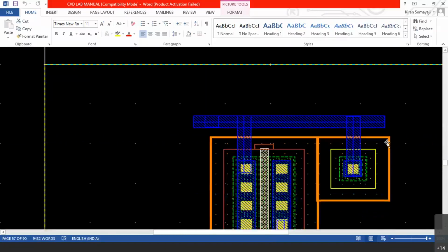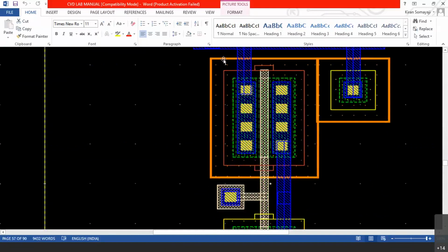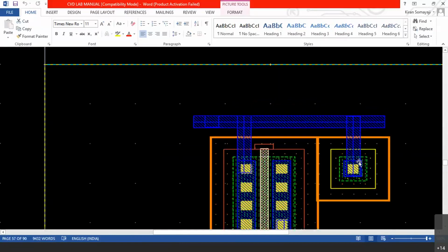What is this one now? This one is P MOSFET in N well. Now the body of P MOSFET is N well. When the body of P MOSFET is N well, the body of P MOSFET must be connected to VDD, right? To avoid leakage current within the substrate or within the body, that particular junction which inadvertently became a PN junction, that PN junction should be reverse biased.